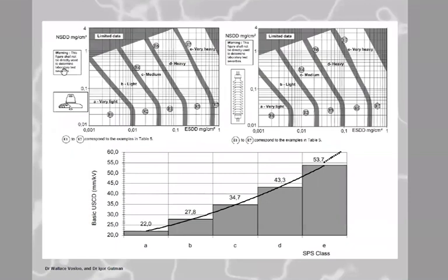And then, yeah, you can see now you measured your non-soluble deposits and your soluble deposits, which is now your equivalent salt deposit density values. And from here, you can determine what's the pollution severity levels in your area. If it's a very light area, very light, you need 22. And if it's B, which is now light, you need 28. And now you see these values are far higher than what we were used to because of the square root of 3. Square root of 3, the little bugger came around and bite you right on the toe, because that's where you make your mistakes, okay?